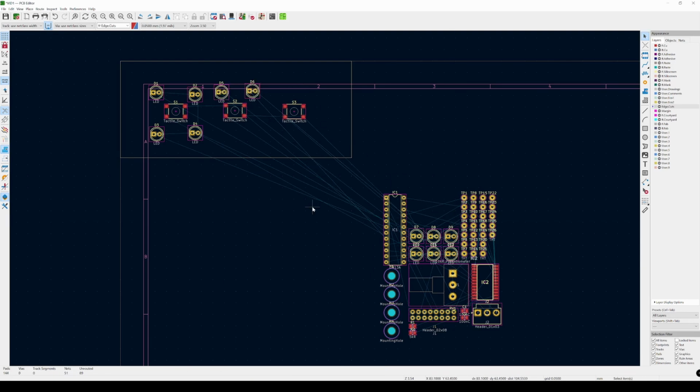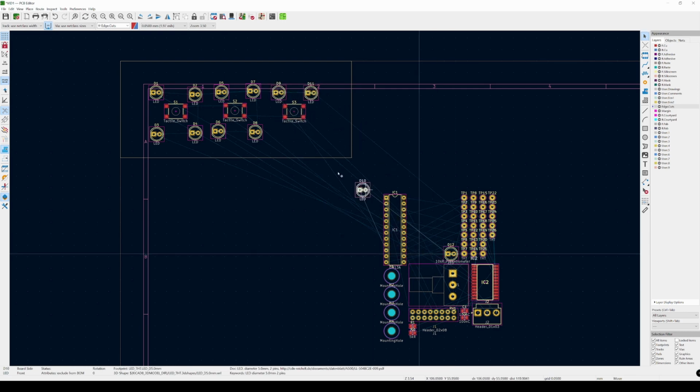But looking at the schematic that we created, we can actually see that for whatever reason, D6 is actually here, and D7 here, and D8 here. It's very easy to mistake, to assume something to be in a specific way, and then that can cost you a lot of time to figure out why things aren't lining up, or even cost you money if you order the PCB and components are in the wrong place.